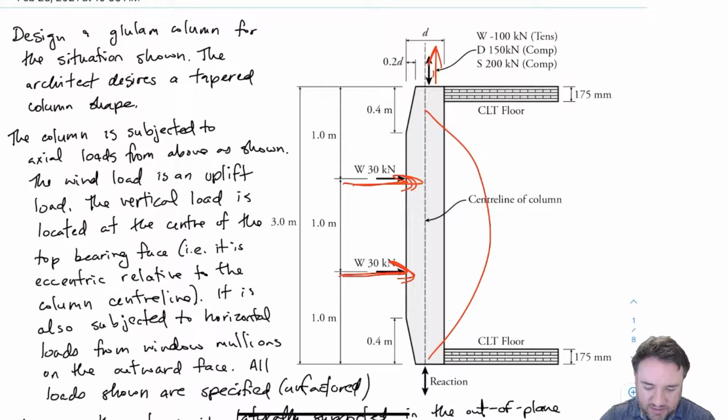But we're going to look at the load combination that's going to cause bending in the same direction as this bulk lateral bending caused by the lateral loads. So that's going to be basically the uplift load. Our governing load combination for that is going to be the wind plus the dead. The dead we're not going to fully get rid of. So how do I find those deflections? I am going to lean on my structural analysis strengths and go to the tables in the standard.